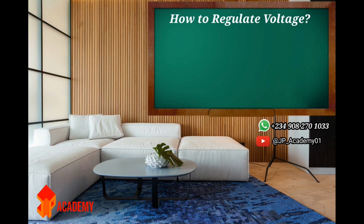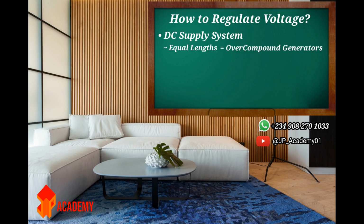Now, in a DC supply system, we can have two possible scenarios. The first scenario is in a case of feeders of equal lengths fed from the DC supply system. And in order to regulate the voltage or control the voltage in a case of feeders of equal lengths, we use overcompound generators.